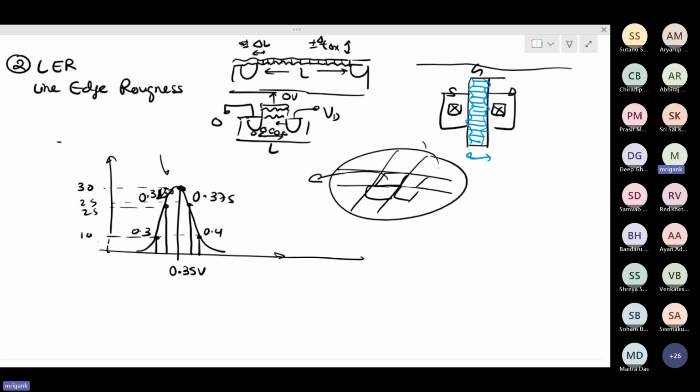Now, suppose this is the NVT, threshold voltage of the N MOSFET. Now, if you had a slow corner, where the MOSFET threshold voltage was more, what will happen? What will happen to this entire histogram? This is a typical TT. Suppose now I have to plot the same thing for the chip in the fast or slow corner. Slow corner, what will happen?